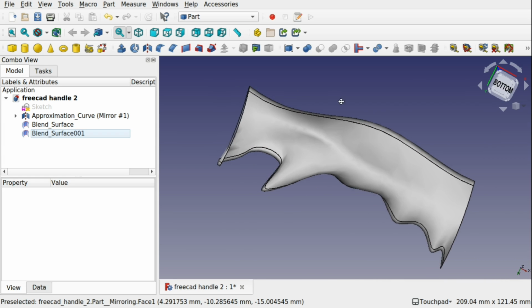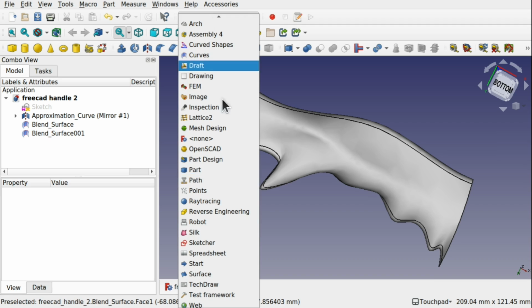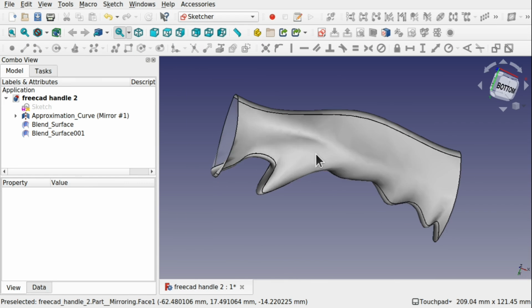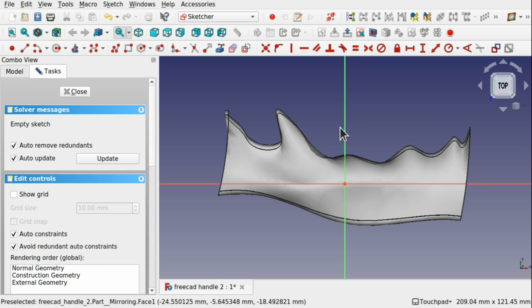What I'm going to use is a small trick with the sketcher, and we're going to make a block around this. So I'm going to come in, create a new sketch, make sure nothing's selected. We're looking along the bottom. Actually, we need to be on the XY plane, the top. Okay, let's flip that around. And I'm looking to create a polyline shape, so I can use lines or create a polyline.